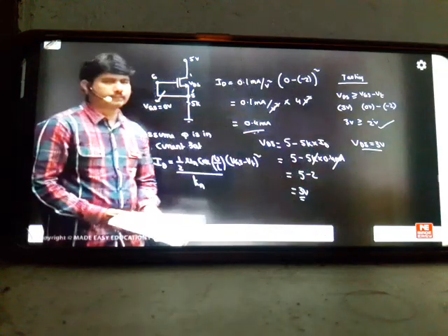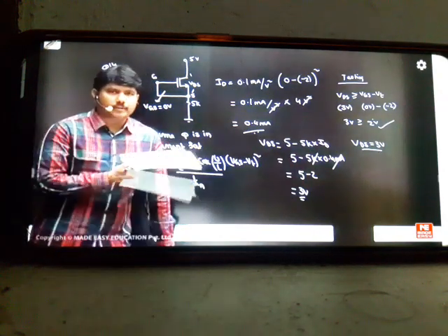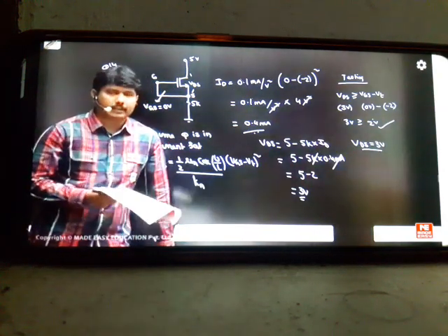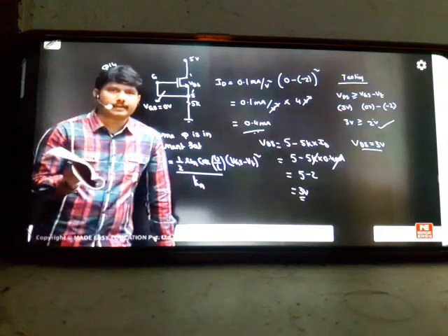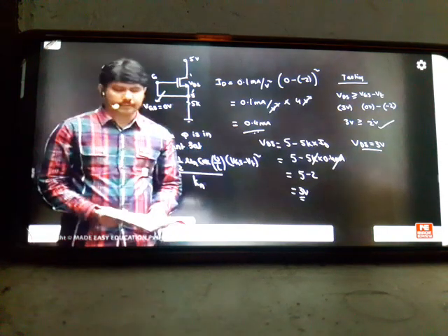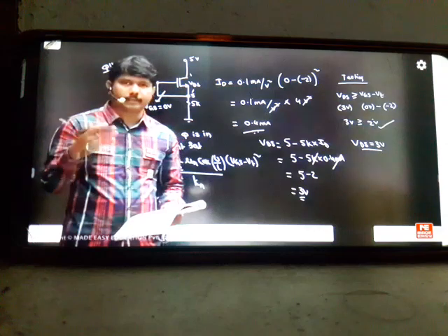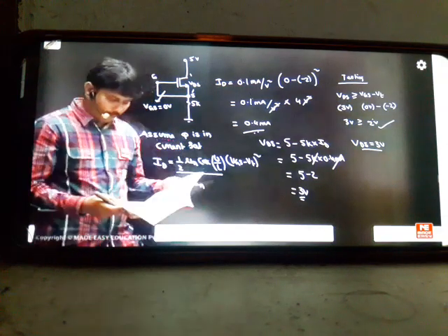So this is the way to do this question. Don't do it directly. They'll try to make this question a triode region problem, then automatically your answer will be wrong. They have a chance to make this triode. So please try to understand why I call it current saturation. This short is not a current saturation short. By chance it became current saturation here, maybe tomorrow it will become triode region. So I hope this is clear.